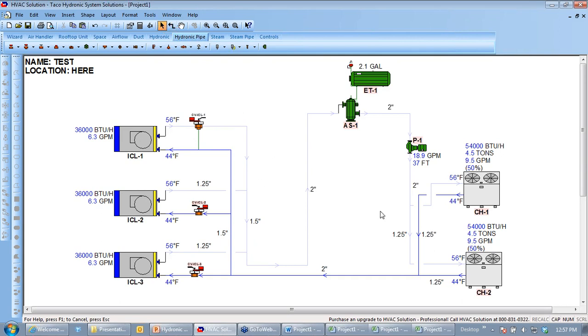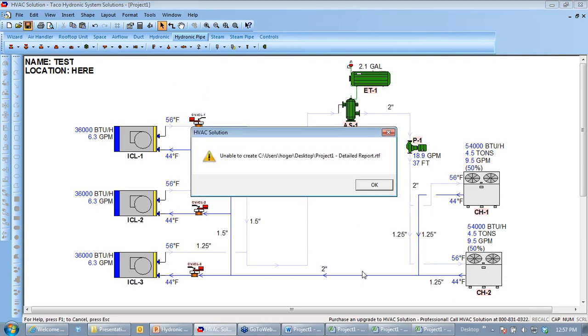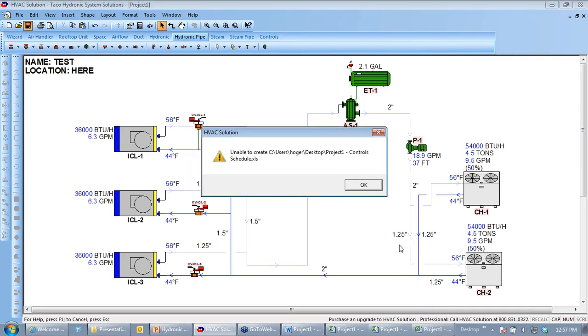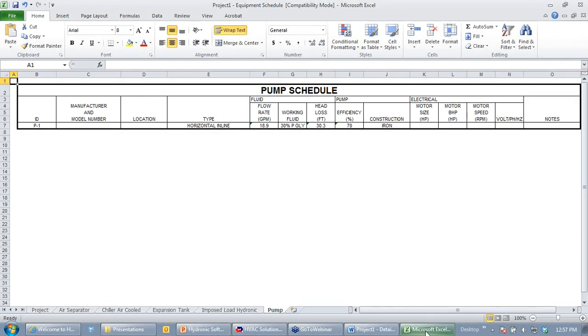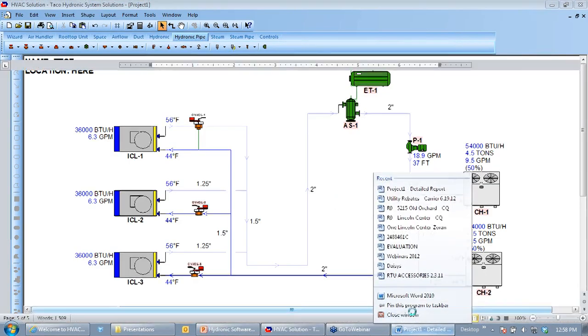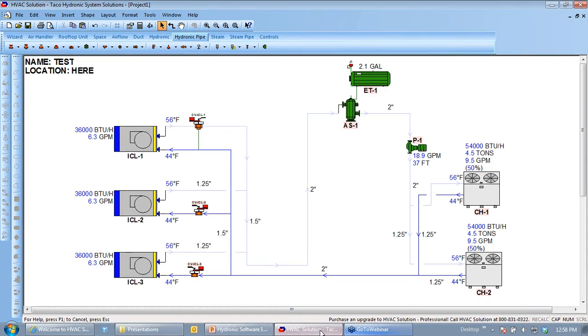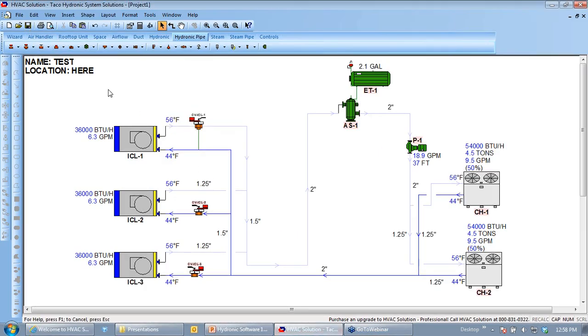Right, so it added those valves, and that'll slightly tweak what I have to do for my pressure drop on the pumps just because of the pressure drop of the valves, but it's pretty minor. But the other nice thing is it'll show up in my reports. So if I were to save this again, oh, I have to close my other spreadsheets, I still have my old ones open. You can't edit the spreadsheet when it's already opened up. So let's just close those real quick. All right, so now back on my drawing, now I should be able to save.